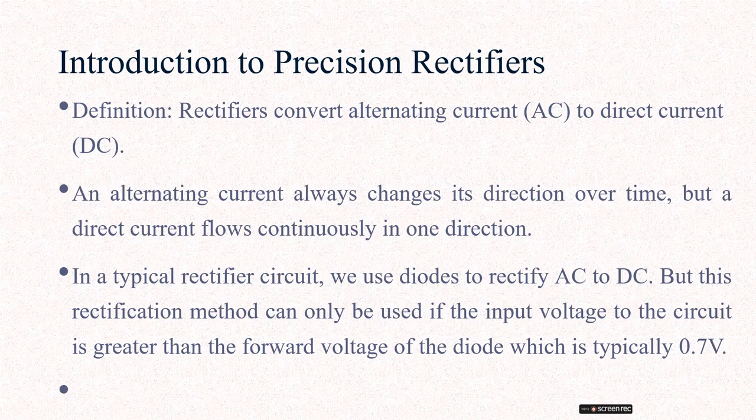So without any loss of voltage, we get the output voltage. We are not losing any threshold voltage, that is the 0.6, 0.3 or 0.7 V drop across the diodes. This circuit is constructed to have some gain at the output of the amplifier. The main purpose is to get the output without any voltage drop across the diodes.